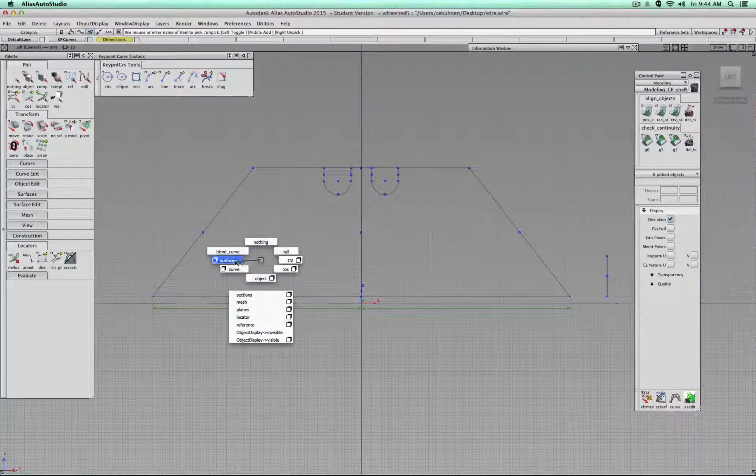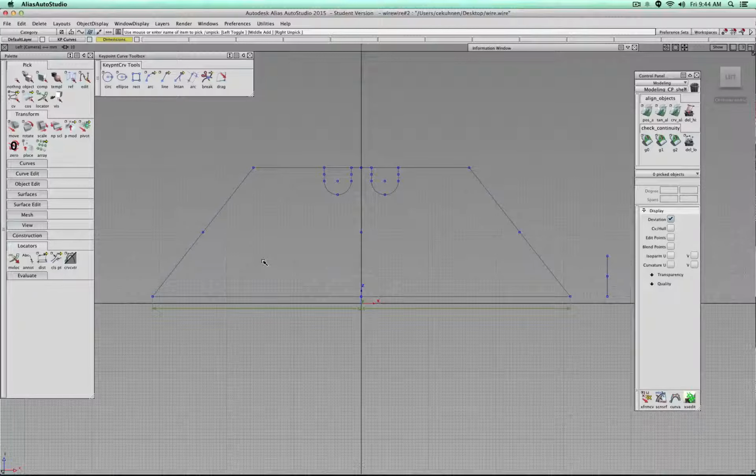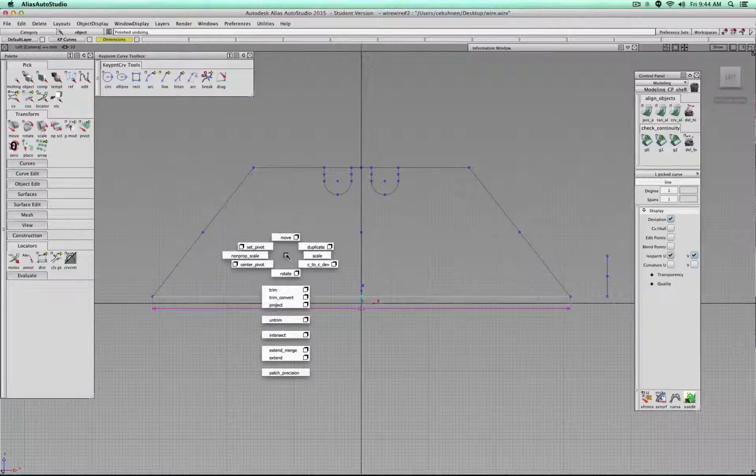So if you memorize the direction and you simply, for example, Shift Control and then move your mouse with the left mouse button up and release, then actually it understands you wanted nothing. If I go Shift Control middle mouse button and up, I know that's where the move is, move. So you see now I can select this one, no, object, move, there. So that's a very nice way to quickly select partial tools when you really know what direction you have to go to.